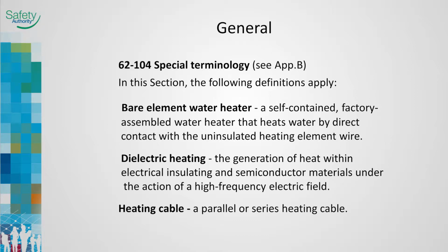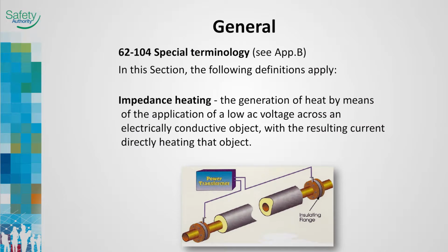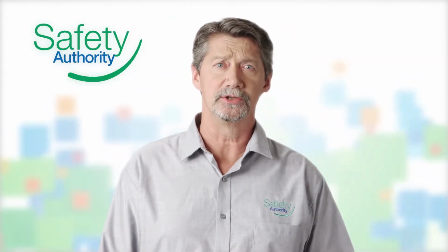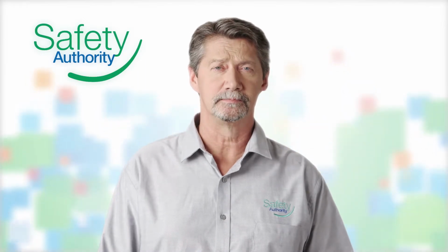Bare element water heater: a self-contained, factory-assembled water heater that heats water by direct contact with the uninsulated heating element wire. Dielectric heating: the generation of heat within electrical insulating and semiconductor materials under the action of a high-frequency electric field. Heating cable: a parallel or series heating cable. Impedance heating: generating heat by applying a low AC voltage across an electrically conductive object. The resulting current directly heats the object. Induction heating is the process of heating a conductive object, usually metal, by electromagnetic induction.